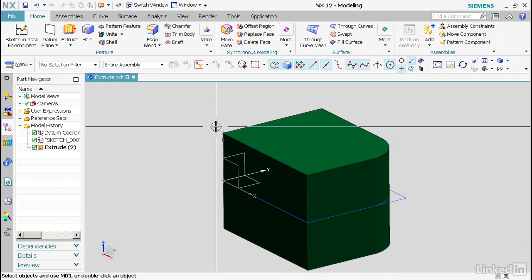So once again, whenever you're doing an extrude, any of these features that require you to pick a section, you want to make sure you have your selection intent set correctly. And once you have that set correctly, then worry about what's going on inside the menu, because what you pick will definitely affect everything downstream. How you pick it, what features you have set for selection intent as well.